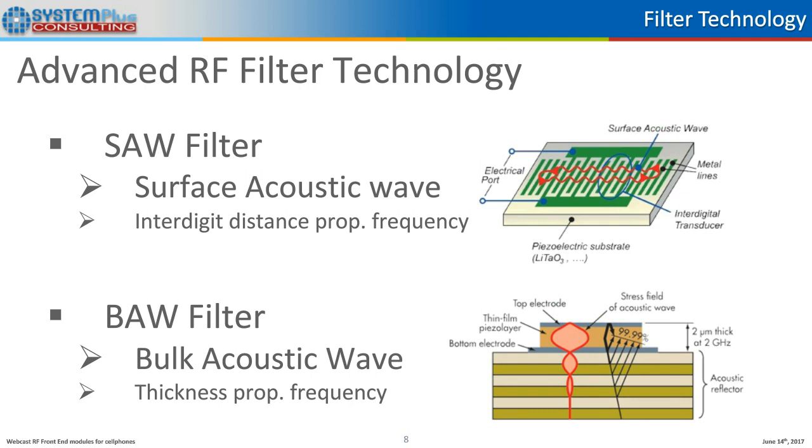This technology is based on an acoustic wave traveling on the surface of the piezoelectric substrate. And the distance between the transducers is inversely proportional to the frequency. And for high frequency, interference issues can occur. And for many years, BAW filters became a better choice.